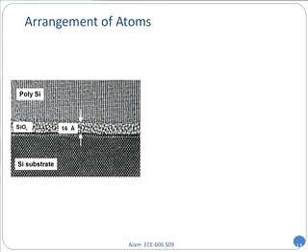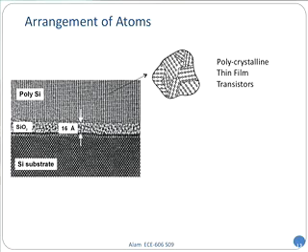This is how perfect modern processing is. You have billions of these transistors, almost this perfect throughout your entire IC. Now, that's crystalline. We use a lot, and I'll explain why, the polysilicon gate. Polysilicon is polycrystalline silicon, where you have crystalline domains of different orientation. That's one type of material that we should be talking about.